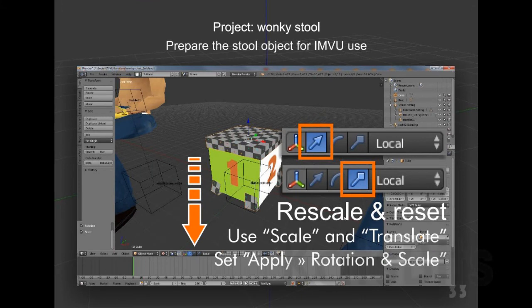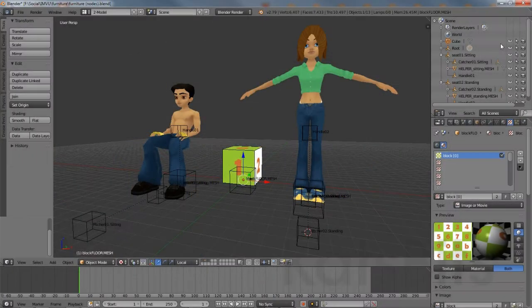Due to a size disparity between Blender and IMVU, the mesh will need to be resized. To make the appended mesh larger, left-click the Scale Manipulator button to activate. Then left-click dragging the white multidirectional manipulator loop near the widget's center. Slowly move the mouse away from the object, increasing its size, matching the cube's breadth and depth. Release left-click to confirm, then left-click the Transform Manipulator button.